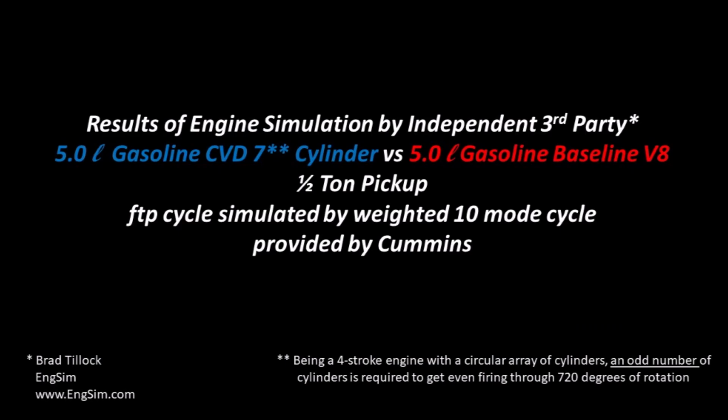In 2012, Brad Tillich's company, InSim, ran GT power simulations for both the CVD and a conventional gasoline engine, including a weighted steady-state 10-mode federal test cycle fuel economy analysis. The effort was sponsored by Cummins, who also provided the test mode values and weighting. Both engines were 5.0 liter and used the same methodology for friction FMEP calculations. The FMEP calculations compared well to calculated values using the Heywood-Sandoval empirical equations.